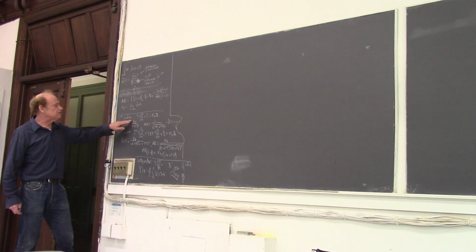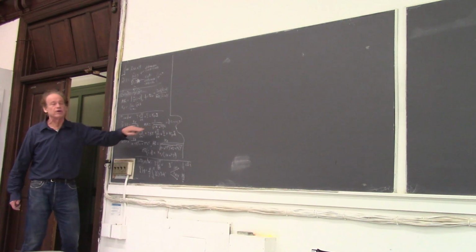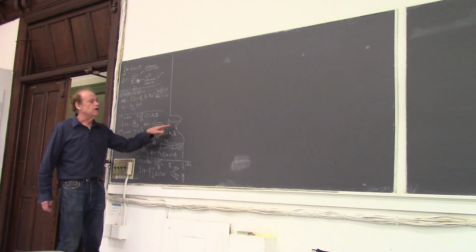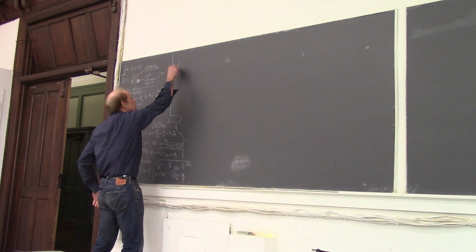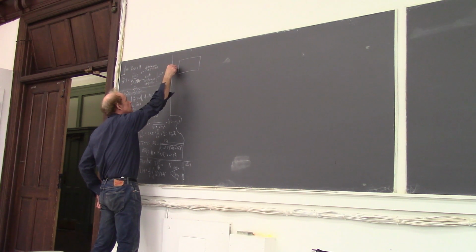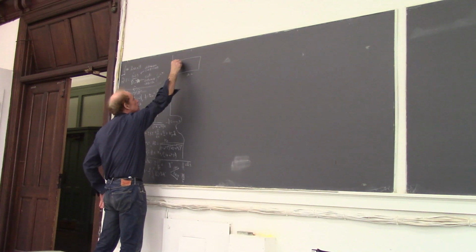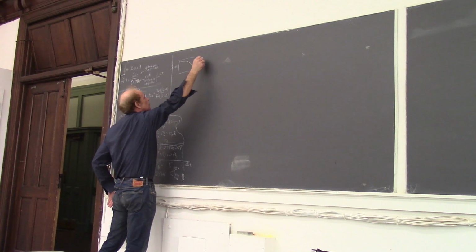And we found that G tilde is Kp over 1 plus s t. And the amplitude ratio was 1 over the square root of 1 plus omega squared t squared. And we found that phi was equal to minus omega t. And we plotted these for a first order system. Where this had a slope of minus 1.